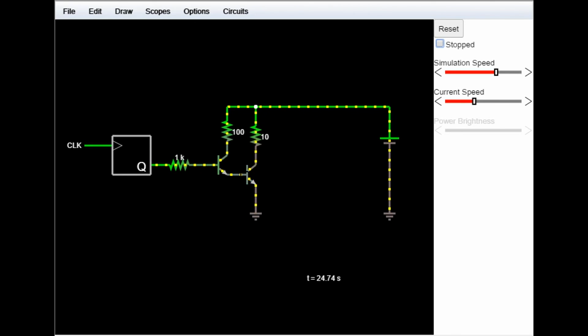Now this transistor is just being driven by that 100 milliamps. So that's enough to have this second transistor running at full blast. 100 times more than 100 milliamps is 10 amps. And so the maximum current that this transistor will allow is 10 amps. Most transistors can't take 10 amps, they'll blow up.